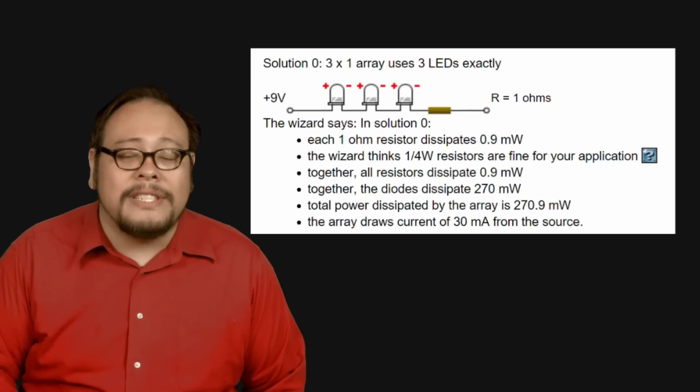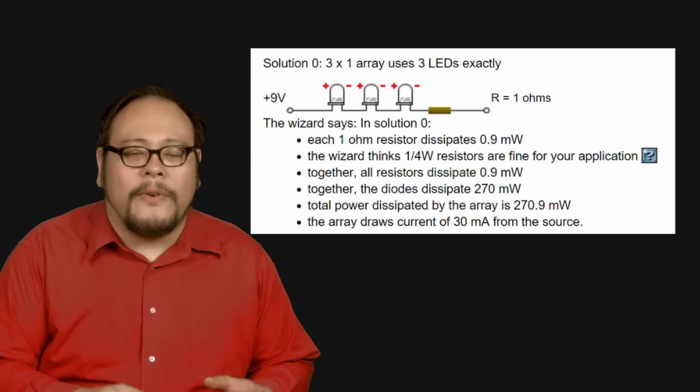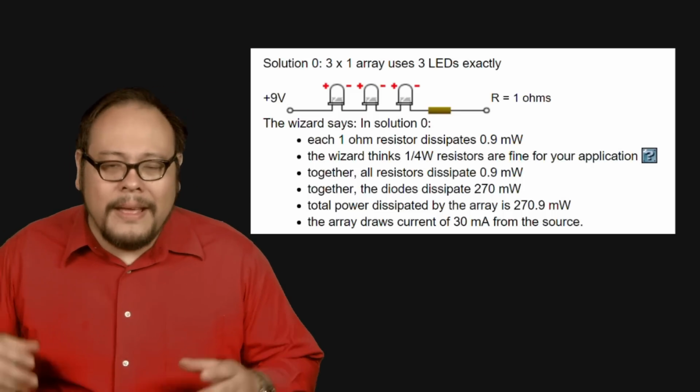Now, the proper thing to do, even when you're wiring in series, is to put a resistor at the end of our series. LED series calculators online will suggest a 1 ohm resistor, even if the series voltage matches the source voltage. But for something as simple as a circuit with a battery where we know we have consistent power and we know the battery isn't capable of huge spikes in voltage, I think you can forego that 1 ohm resistor. Now, if you're an electrical engineer building something that's going to be mass produced, that's different. But we're just hooking up small projects for short periods of time, I think you can forego it. Go ahead and crucify me in the comments for saying that.